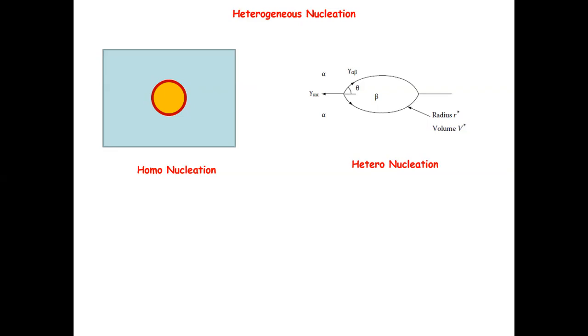If you count them, triple points are much smaller in number than these binary grain boundary areas. So that makes binary grain boundary heterogeneous nucleation the most commonly seen scenario for heterogeneous nucleation in this system.